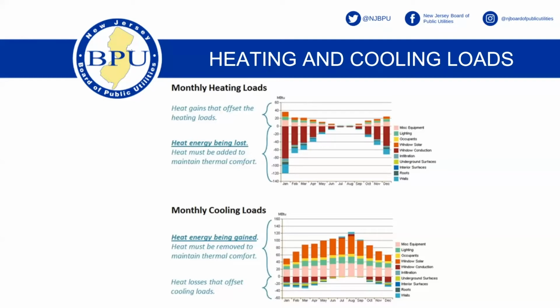And then you want to look at those things. You want to look particularly first at the shoulder months and ask yourself, do you use more or less fuel in the summer than the winter? In the fall and the spring, are you heating less and cooling less? And if you're not, there's something running all the time.